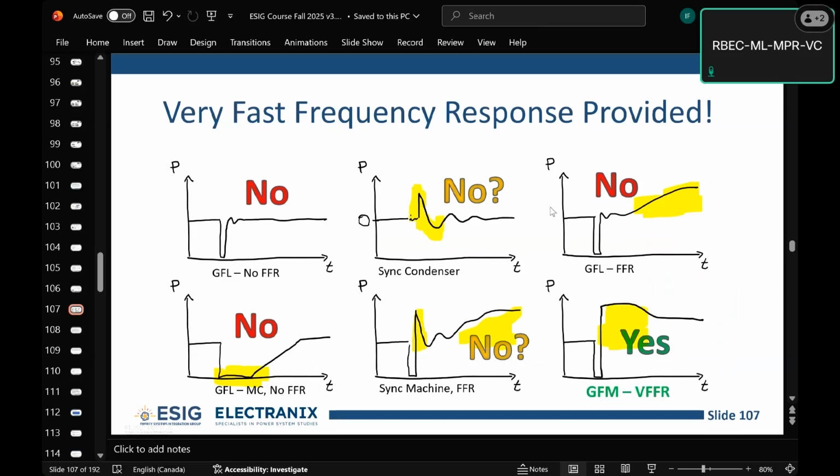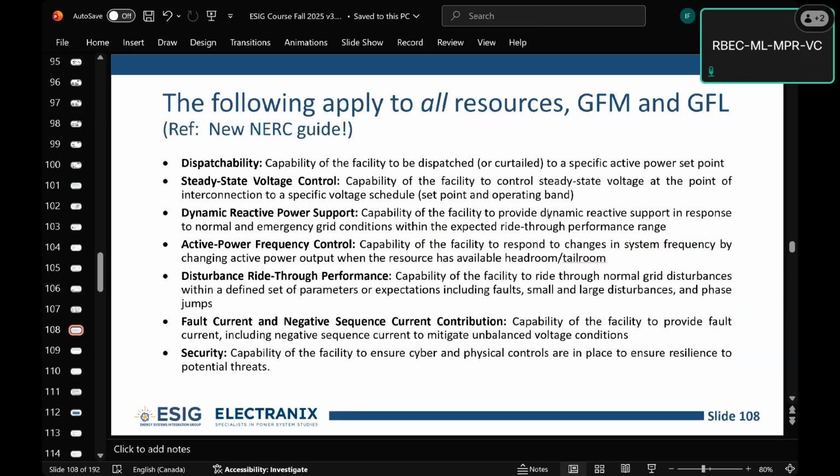I had another slide in here, but I didn't put it in. Basically, another thing to think of is using it with HVDC. There are a number of HVDC grid forming plants in the world. If you put grid forming on one side of an HVDC link, that essentially strengthens that side at the expense of the other side. So it will move current in and out of the weak side to strengthen it, but the other side has to give you that current. So you can think of an HVDC line with grid forming as a pipeline for grid strength, kind of. So you can move system strength from one region to another through HVDC with grid forming. So it's another application.